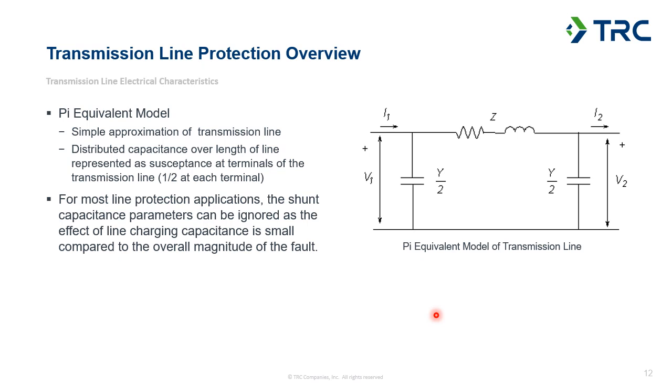You can go through and run the math and do it. We've got a bunch of engineering tools we use that will do some of that modeling for us based on that same input information, the electrical characteristics of the conductors, the locations and spacing and sag and height of the conductors, and it'll generate an electrical model of the transmission line.